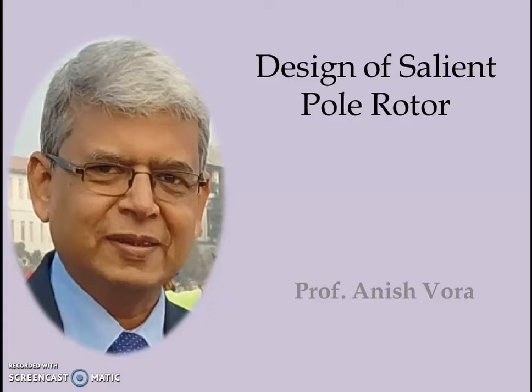Currently, you know that we are running a series of video lectures on design of synchronous machine. In this video lecture, we will study the design of salient pole type of rotor. In case of synchronous alternator, we use two different types of rotor construction: one is salient pole type and one is smooth cylindrical type. In case of turbo alternator, we use a smooth cylindrical type of rotor construction, and in case of a hydro alternator, we use a salient pole type of rotor construction.